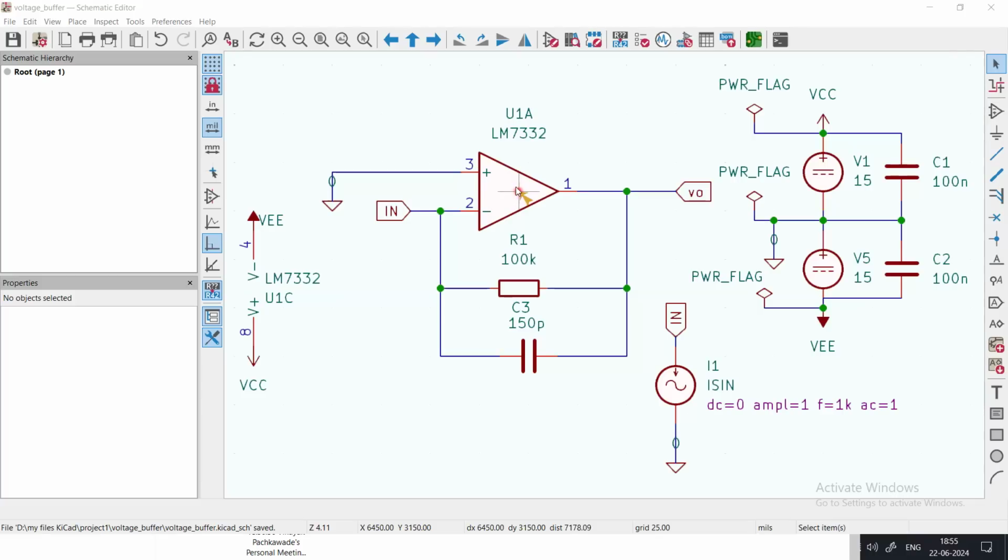So this hardware part I have explained to you in our previous model, how I got access to the spice model of this amplifier IC, how I downloaded it into my computer, how I added the directory, and how I mapped the symbol pins of the KiCad of this part to its model pins.